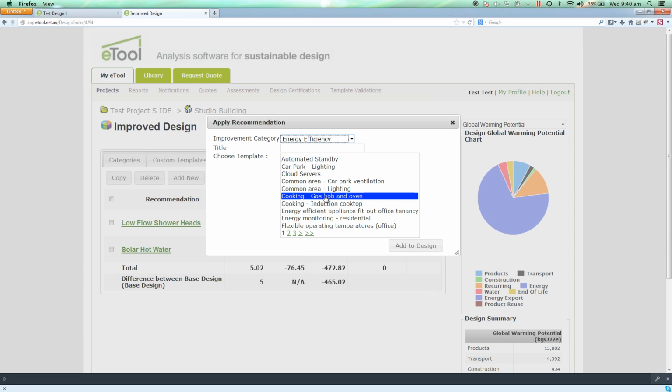So we're sort of assuming here that in a lot of grids, it would be better to use gas for cooking rather than electricity, because you're burning it at the end use source rather than wasting 70% of the energy somewhere in the electricity grid. But if you're on a low carbon grid, if you actually modelled this, you'd get a negative improvement, if you like. You get an increase in impact, certainly in terms of carbon anyway. So these aren't necessarily definitely going to be fit for your building, but it does give you an idea of things you can consider doing to improve your building.